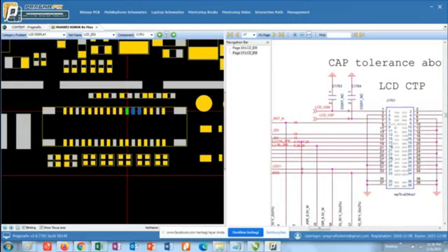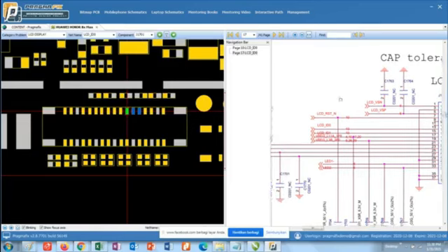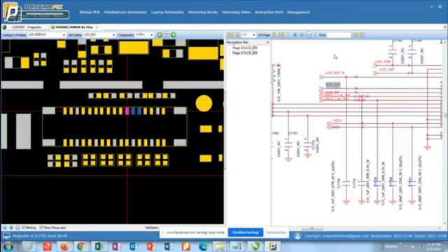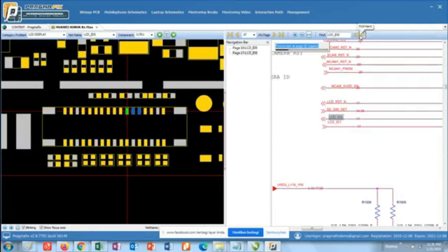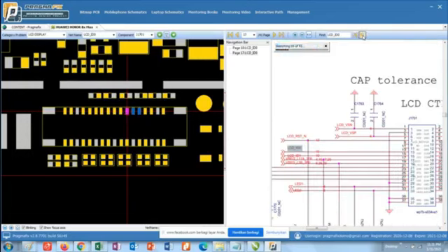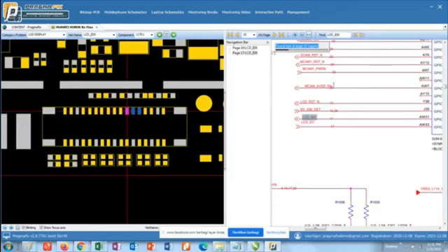So this is all automatic. For example, this one has 34 pins for sure, data 0, or this is pin number 13. I think this can help you guys work faster, and this will be connected to LCD data 0. This is no longer speculation anymore. To look for where LCD data 0 goes, just copy, continue, paste, and search again, and surely it is directly connected to the CPU.